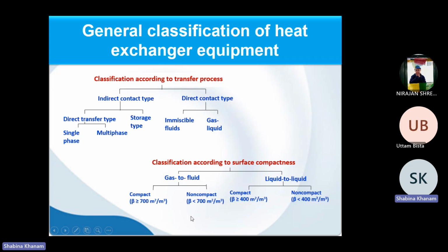If you ask what type of heat exchangers these are, these are very small, if you see the size of that. These are used when we have a surface constraint, when surface is not available in a larger amount. We can have this compact heat exchanger. To give an example, like aerospace, where space is literally limited, and there we consider the compact heat exchanger. These compact heat exchangers are used in cryogenic conditions also, where the conditions are very severe and it cannot be placed in a larger area, so we consider compact heat exchangers there.